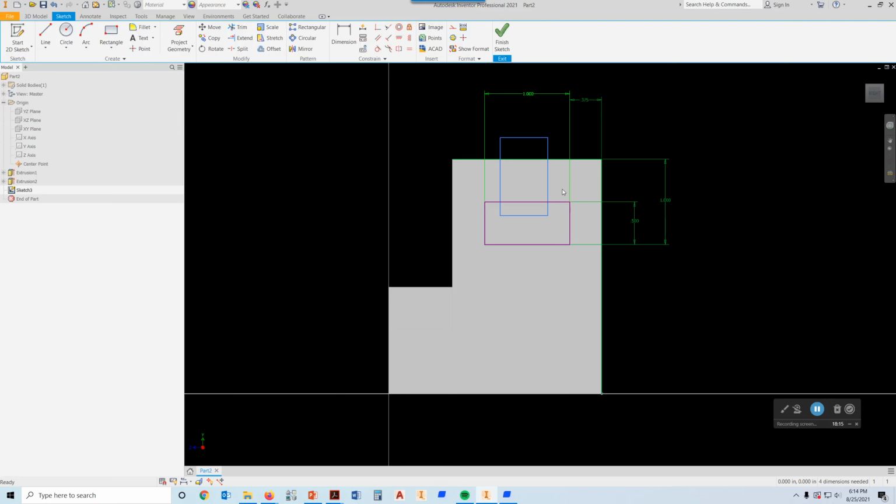So I'm going to go ahead and define this rectangle that I put in over here. So first I'll place a dimension from the right side. I'm just going to pick on the right side of the model, and then I'm going to go to the right side, move a dimension right up there and pick. And I want that to be 0.75 and press enter. Okay. The next one that I want to place, I'm still in the dimension.